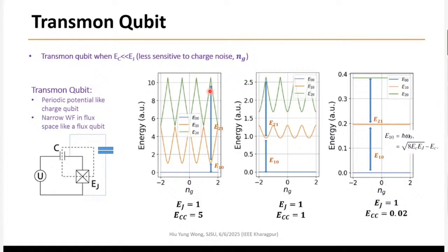Okay, why? Because the regular Josephson junction has very bad charge sensitivity. It is very sensitive to the noise outside of the world. So let's take a look. For example, this is again the qubit we just discussed. We have a Josephson junction here, and this is the capacitor in parallel with it. Now, I have a tiny capacitor, and I couple this system through this coupling capacitor to a voltage. Then it will create some background charge, Ng.